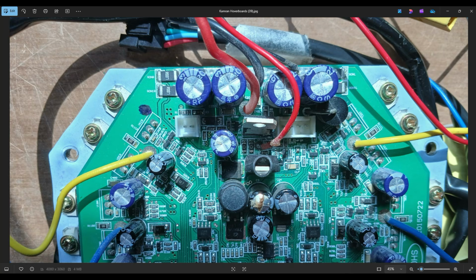Therefore C equals minus (A plus B). That is a math calculation. The purpose of using two shunt resistors is the best balance of cost and performance, and it is used on all STM32 motor workbench hoverboards.